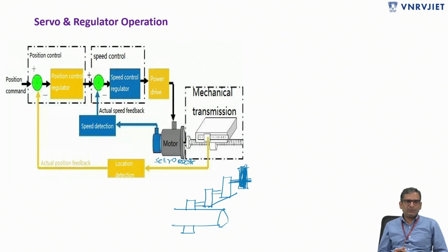Then, as we know, to change the speed of the motor, or we can say the torque, it is proportional to the armature current Ia if it is an armature control motor. So by changing the armature current we can easily change the torque of the motor. To change the speed we can make changes in either Ia, the armature current, or Va, the armature voltage. So the first one is the position control.